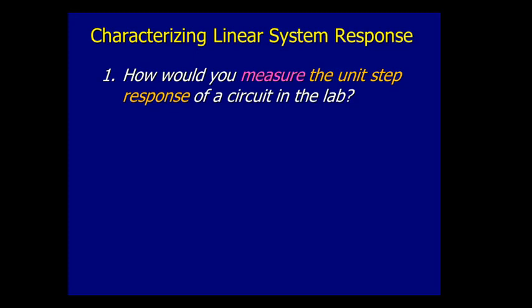So the problem you're working against, if the circuit reacts quickly, right? You want it to be settled out before your signal goes away. If it's really slow responding, it's not done by the time this goes away, well, you're going to get a false measurement. So we want to make sure we're on long enough to let the circuit response finish dying out with that on time before we take the signal away.